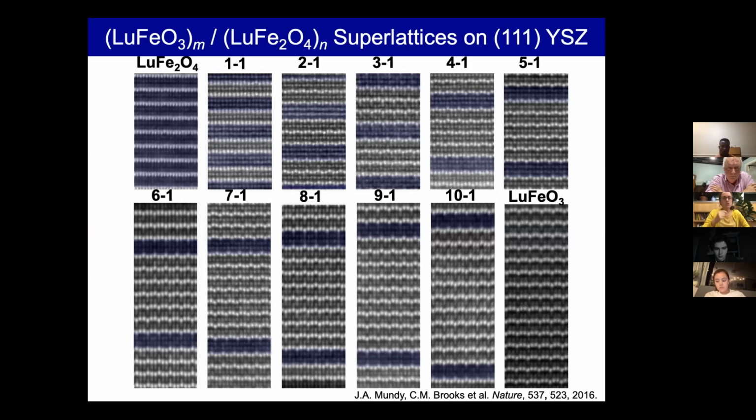Yeah, so you're looking at these pictures right here. There are two things that we can control with the rumpling. The atom spacing in this compound, we can impact a little bit with the underlying substrate, but materials do have some equilibrium bond length, covalent bonding. So I can't separate the atoms 5 meters from each other or even 5 angstroms. They're fixed to some rough length scale. Most of these atoms are about 2 angstroms apart from their nearest neighbor.